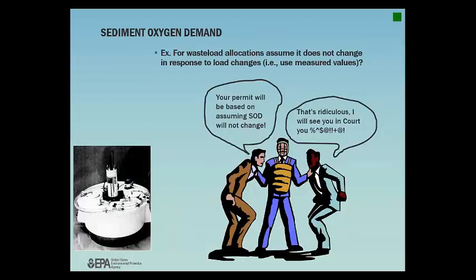There have been many TMDLs and waste load allocations developed in the United States that did have an SOD component. Unfortunately, when the load reductions were calculated, there was no real good way to attenuate the change in SOD as a change in the loads. And in essence, we may have been over-regulating or not accounting for the changes in sediment oxygen demand as a function of the overall loadings to the system.